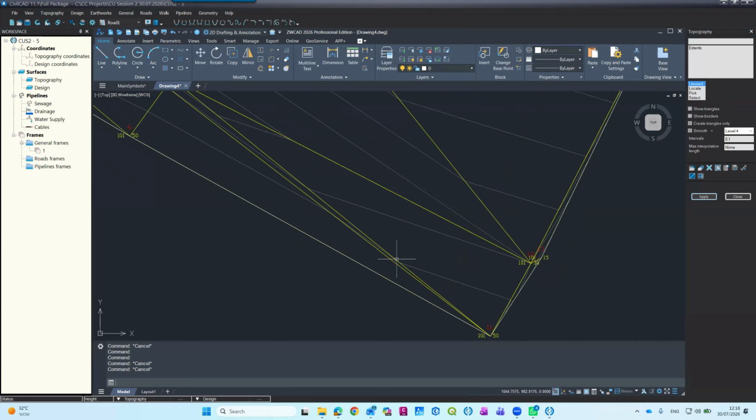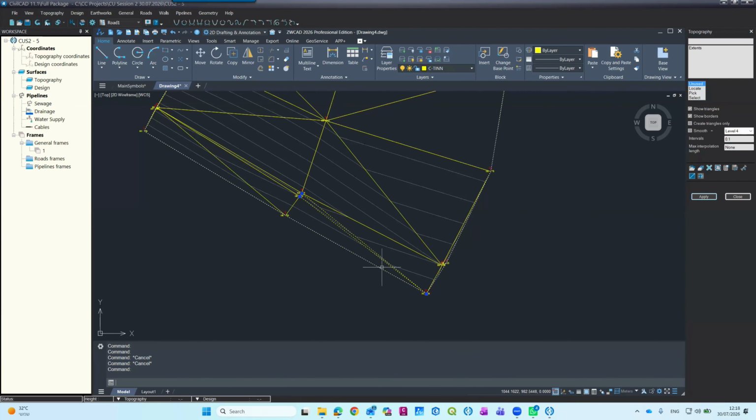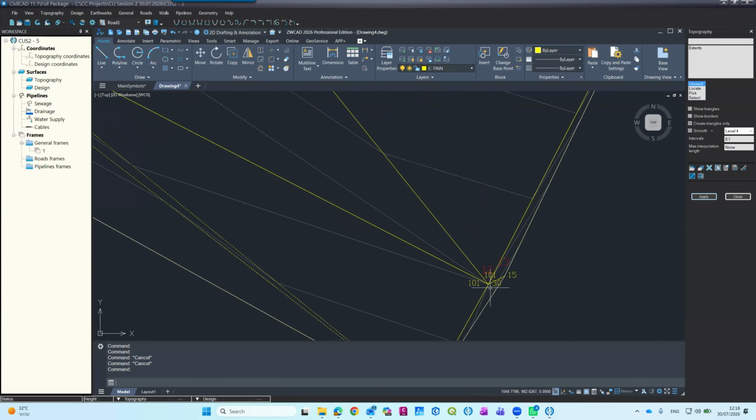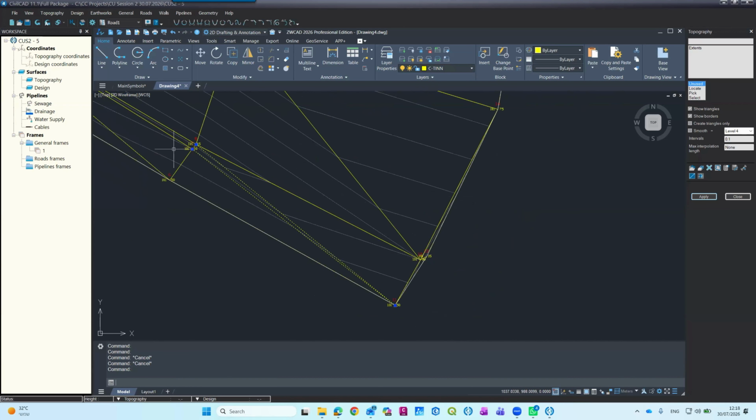Here, especially here, you see they are breaking, and you can see it immediately. They are breaking because of this triangle. This triangle was created because the software, as we talked about, takes the 3 nearest points and does a triangulation. The software doesn't know that there is an end of a sidewalk here.